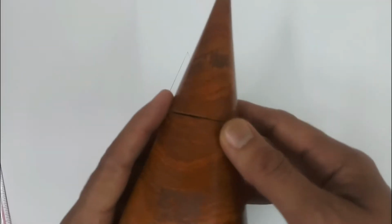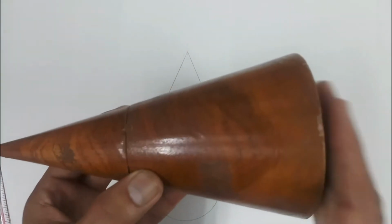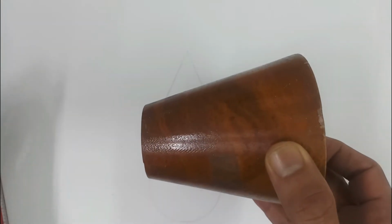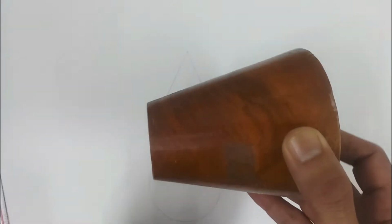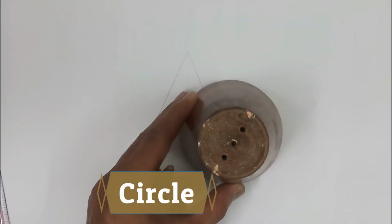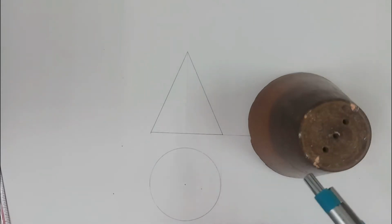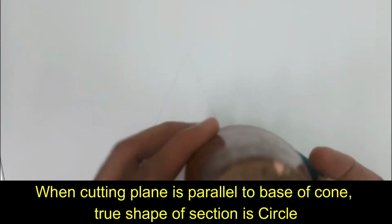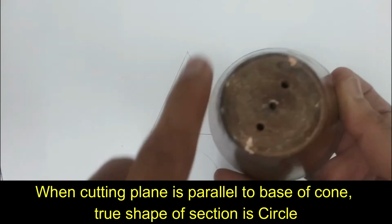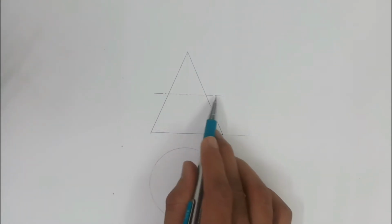If I cut this cone by a cutting plane which is parallel to its base, as we see here, this is the base of the cone. So if I cut by a plane which is parallel to the base and remove this top portion containing the apex, then you can see the section. How is the section? You find here that the section is like a circle. So the true shape of section is a circle. Whenever a cone is cut by a plane which is parallel to its base, the true shape of section obtained is a circle.